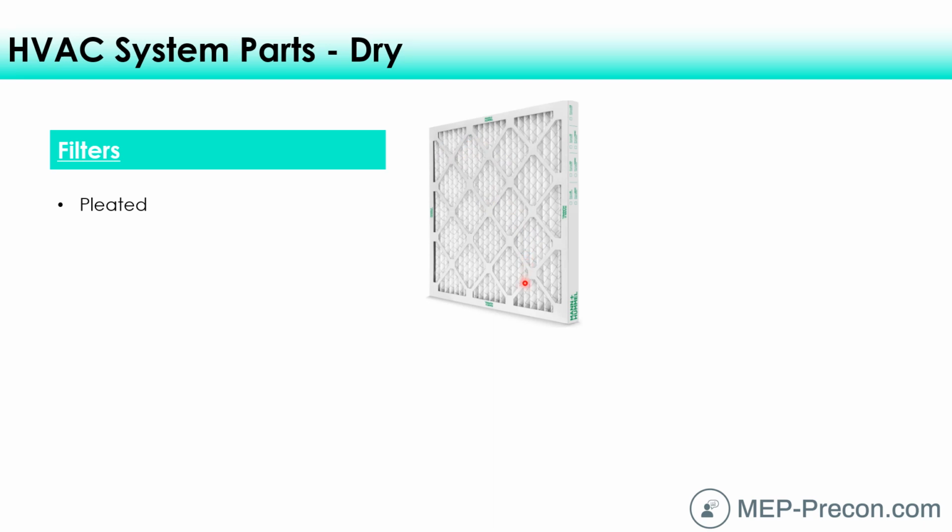but also it reduces the velocity through the filter, because this media has an upper end of velocity where it works well, and that's usually around 200 or 250 feet per minute. And within the ductwork, we usually like to design it a little bit faster than that so we can have some economies of not making the ductwork so big and using a lot of expensive sheet metal.